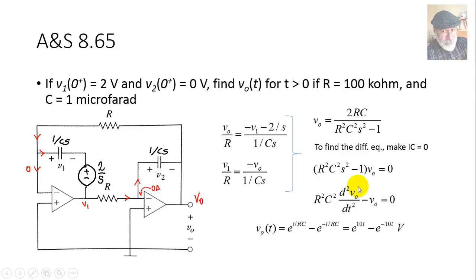When we find the inverse Laplace transform of this expression at the top, we get the sum of two exponentials. But check it out. While the second term, the subtracting term, will die off 5 over RC seconds later, the first term keeps growing without bounds. This circuit is unstable. I have replaced R and C's values into this expression to get the final answer to the problem. That is V0 as a function of time for this unstable circuit.